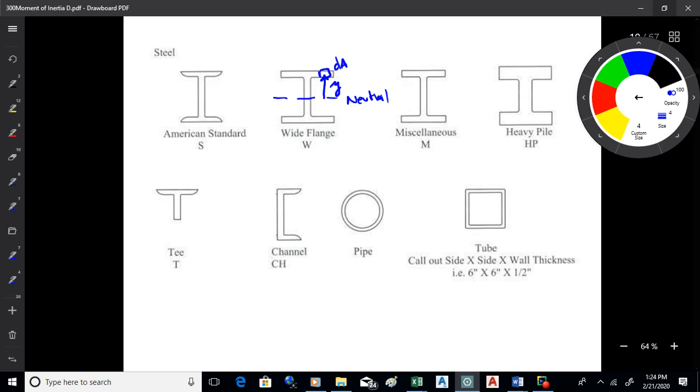That's what you're attempting to do. Those are the flanges. You want the flanges set out away from the neutral axis. Now, as best you can, obviously you can't have an I-beam for a house that's 4 feet deep, that's ridiculous, right? So you have to keep it within the constraints of what you're trying to build, but that's the basic idea of an I-beam, okay?